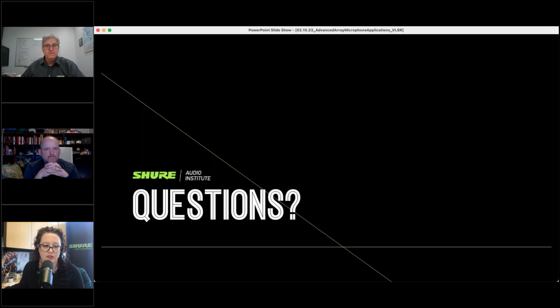All right, next question, and one for actually you two. Are there RT60 and NC benchmarks to qualify a system for voice lift in addition to the minimum room size? Not that I'm aware of. I'm sure if we dug up recommendations, we could find them. But based on what we're doing here today, I'm going to go off the PAGNAG calculation as my gut check, right? If I need those measurements down the road, then I would take a look at that. But I don't believe we have any kind of minimum recommended or maximum recommended RT60 numbers.